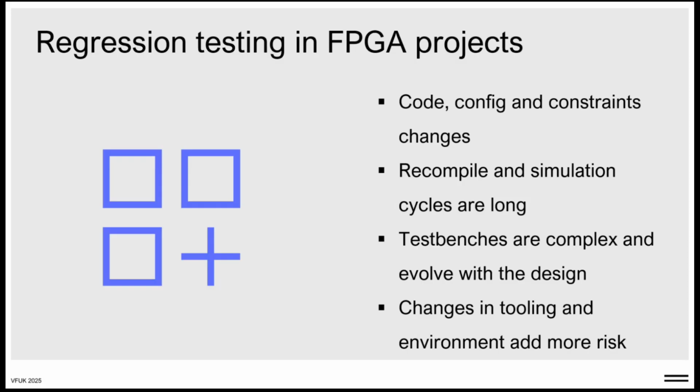FPGA projects are especially sensitive to regressions. Any change to code, constraints, or tooling can lead to problems. And simulations are long, test benches are complex, and changes ripple. So that is why FPGA projects need good regression strategies.